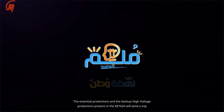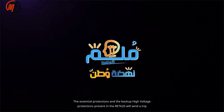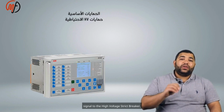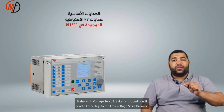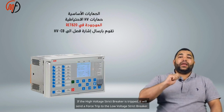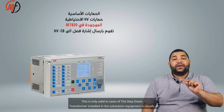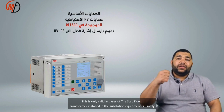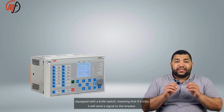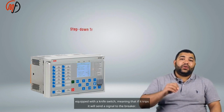The essential protections and the backup high voltage protections present in the RET620 will send a trip signal to the high voltage breaker. If the high voltage breaker is tripped, it will send a force trip to the low voltage breaker. This is only valid in cases where the step-down transformer installed in the substation is usually equipped with a knife switch, meaning that if it trips, it will send a signal to the breaker.